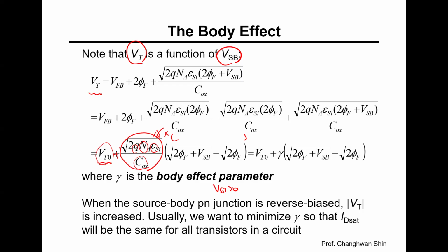However, the body effect can also be intentionally utilized in some circuit designs, such as substrate bias generators or variable threshold logic. So understanding and controlling this body effect is crucial for advanced analog and digital design, definitely. Which is very similar to how understanding how temperature affects materials allows engineers to compensate for or exploit these effects in their designs.